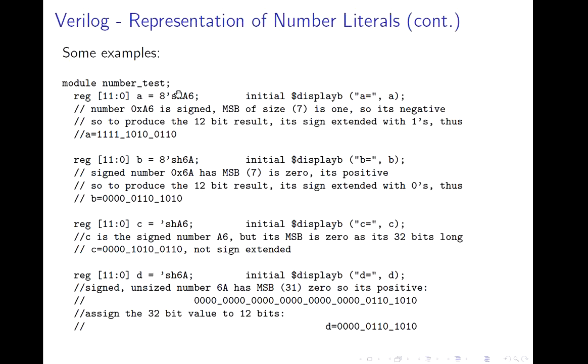On a similar note, let's interchange this number. For example, I want to store 6A in a 12-bit register. Now represent 6A in 8-bit form. That will be 0110 1010. So this is my actual 8-bit number. Now again, this number has to be stored in a 12-bit format. The MSB of this actual number has a value of 0, so you append the remaining bits with 0. Look at the difference. What value the MSB has matters when appending the previous bits, and that too once you get this 8-bit formation, because you have represented it here as 8-bit, right?